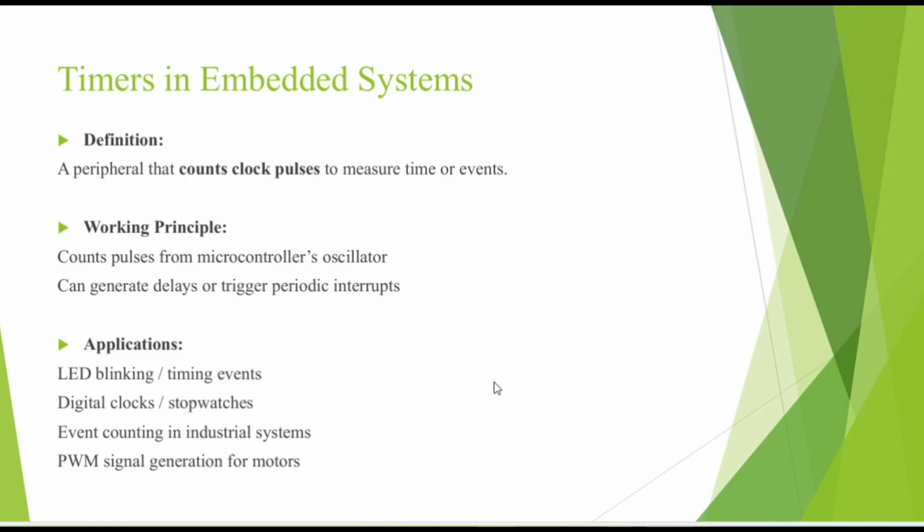The working principle of the timer is to count the pulses from the microcontroller's oscillator, which can generate a delay or trigger periodic interrupts. There are some types of timers like basic timers, PWM timers, watchdog timers, and real-time timers. The applications are LED blinking or timing events, then digital clocks or stopwatches.